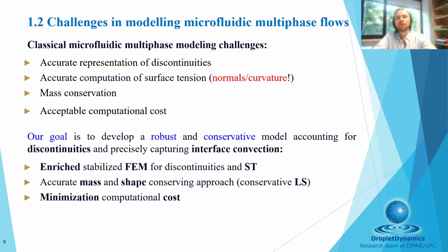So you have both discontinuities in the pressure gradient due to the change of the density and the jump in the pressure due to the presence of surface tension. So unlike the typical continuum surface approach, where the surface tension is spread at a finite width interface, we managed to really model the surface tension related effects on an infinitely thin boundary.